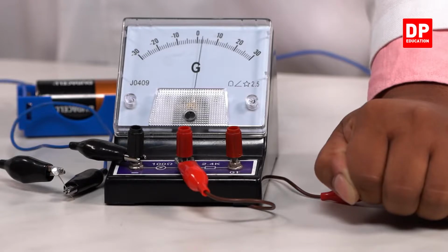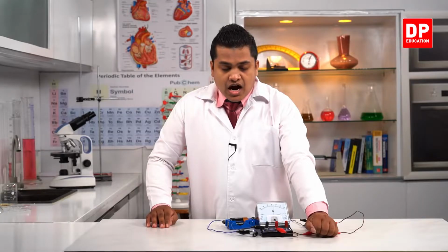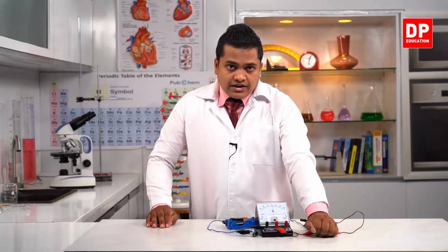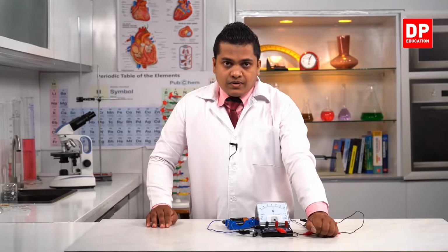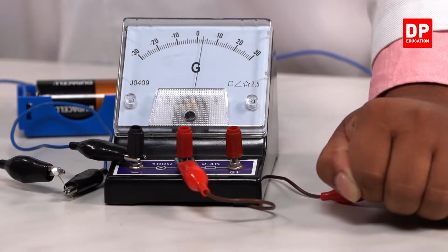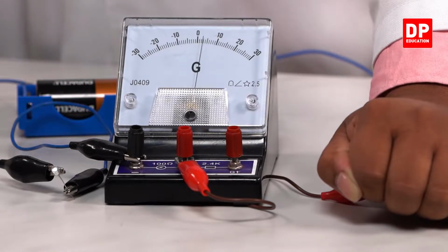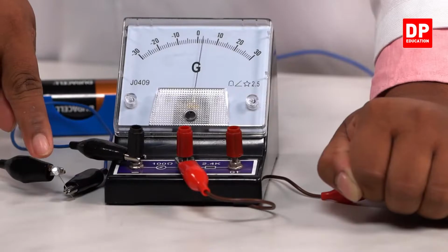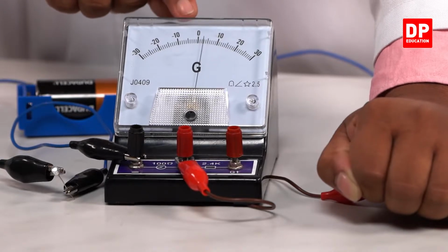It's because when the intensity of light around the environment is reduced and less light energy is received by the LDR, the resistance is high. If there is high resistance, current flow is low. So that's why when I'm covering the LDR like this, there is less light from the LED and the reading is nearly 0 now.